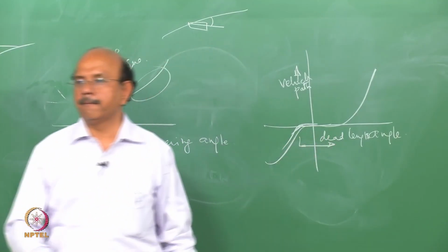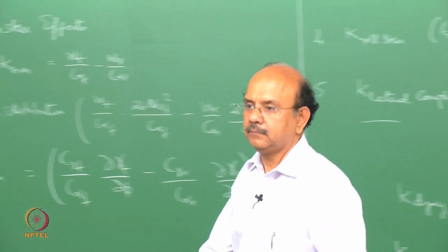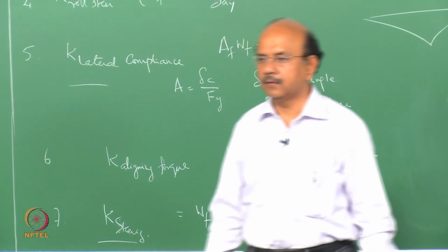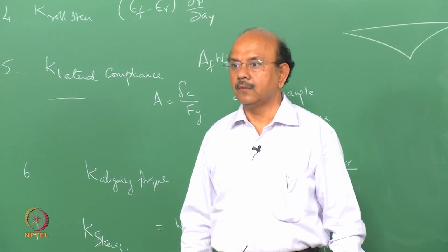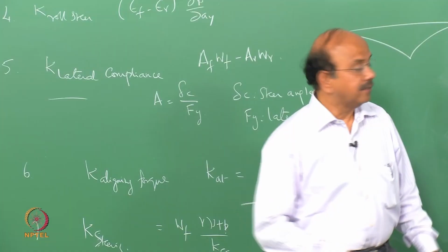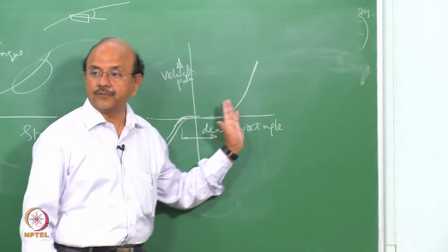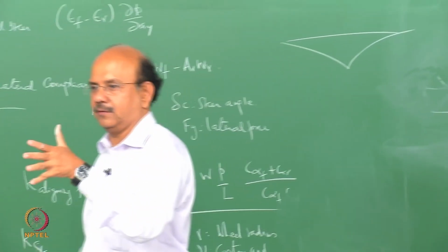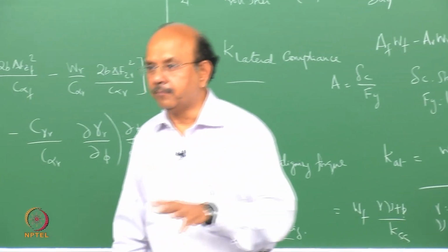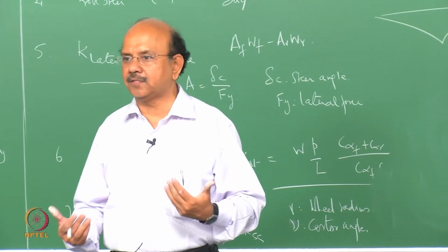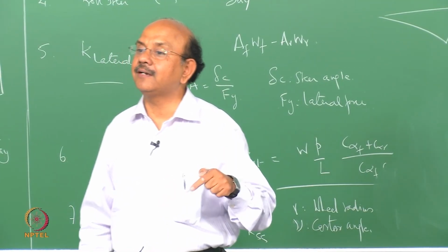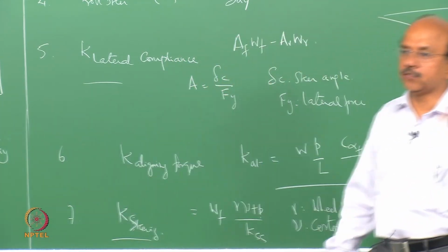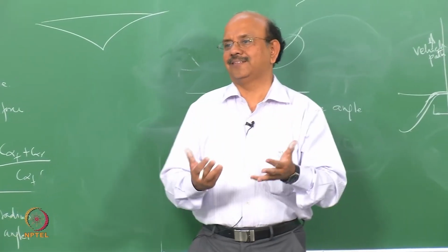Clear? So you said the reason for having that dead zone was so that disturbances wouldn't cause changes in the vehicle path. But if that disturbance happened when your steering angle is not at the dead zone. No, that's correct. If it is off, that's what is called off center. If it is off center, and if there are disturbances, you have to control, no doubt about it. But when you are going straight, I do not want the disturbances to be affecting. That directly impacts your fatigue, right? Because when you go straight, if you keep on turning, the fun is lost.